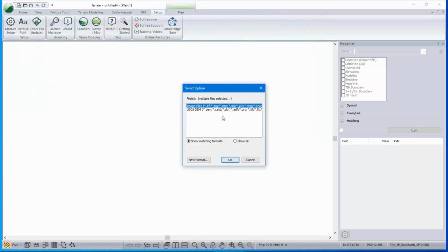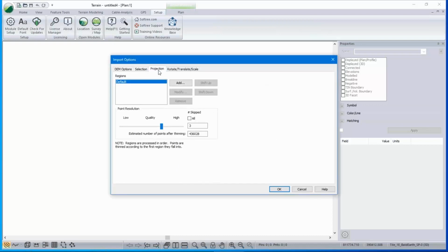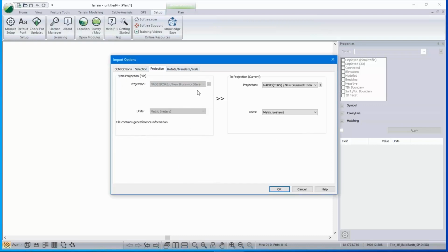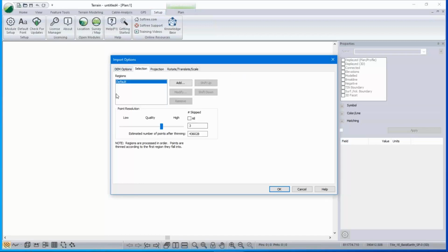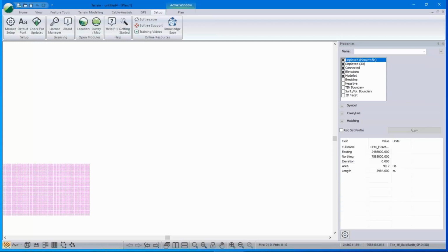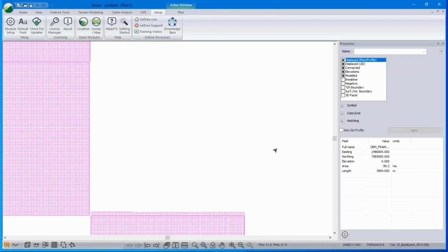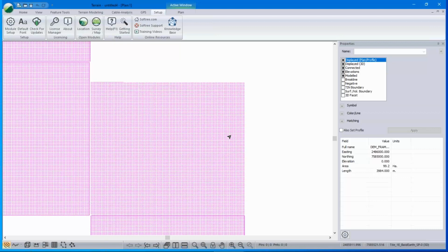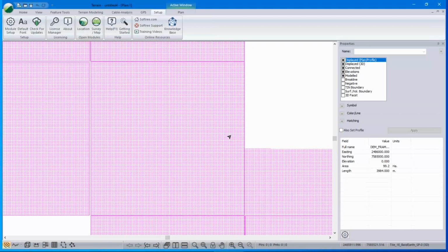So if I want to reduce that, I can just thin it. And this is a great way to work with DEM files. Thin the data at read time. It turns out that the skip 3, read 1 for a DEM is actually skipping 3 rows, reading 1 row, and then skipping 3 points, reading 1 point. So it's actually reducing the number of points by quite a large amount, not just a factor of 4. I've set it to reduce the number of points that are being read right from the hard drive, so I never fill my screen with too many points.